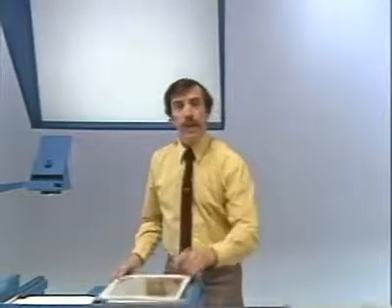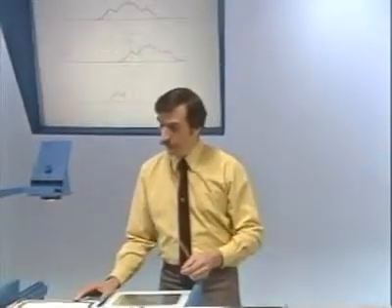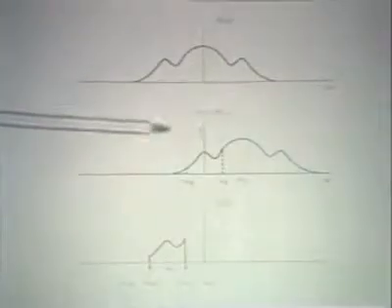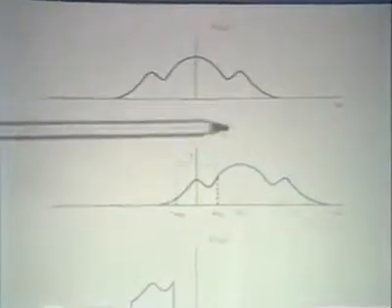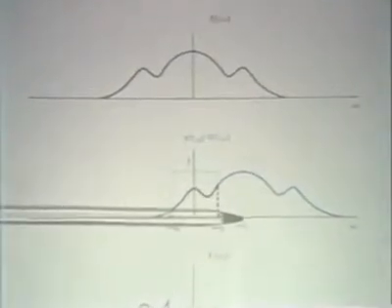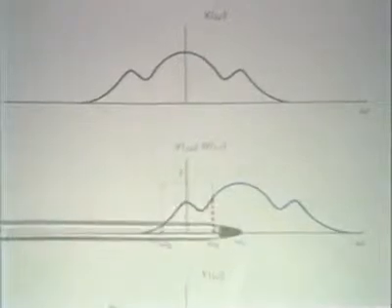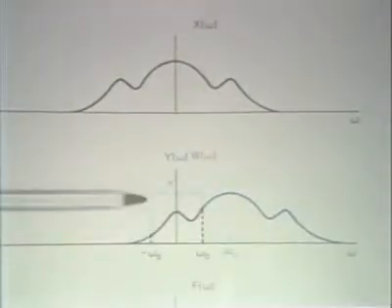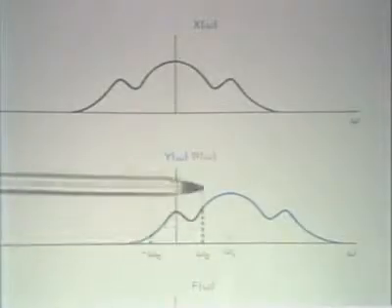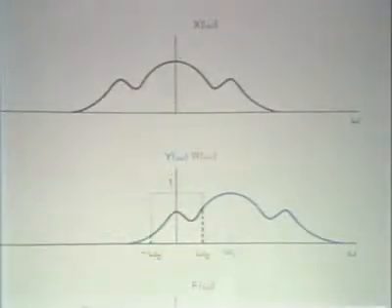So if we look at that in terms of actually tracking through the spectra, we would have initially a spectrum for the original signal, which I show at the top as x of omega. After modulating or shifting that spectrum up to a center frequency of omega c, we then have what I indicate here, and the dotted line corresponds to the passband of the low-pass filter.